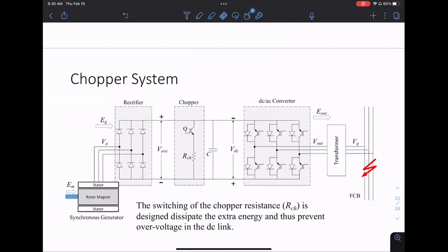But because the power is very high, a lot of large energy is flowing through this capacitor, being sloshed around in it. So that's why it tends to break. That's why the material is important. And again, large capacitors are very expensive, so this capacitor is important. You have to have this decoupling capacitor here, right?